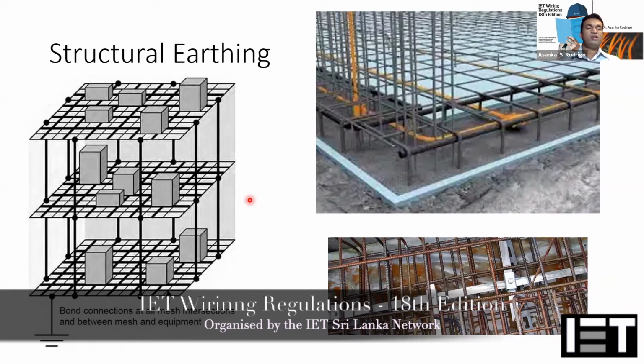Normally, when you look at the IEC 62305 standard, it talks about three different options of earthing arrangement. One is that for every down conductor you can have individual earth electrodes. For example, when you look at these down conductors, you can have earth electrodes like that, individual for each down conductor. Now they are connected all together, where you can have an earth pit like that, or even a ring earthing system like that, connected together. That option is also available.